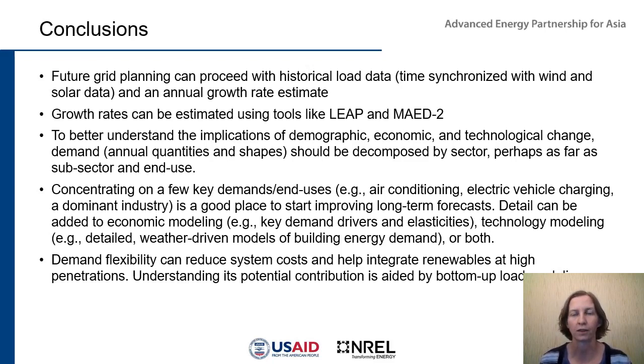So if you're thinking there's going to be a lot more electric vehicles, or there's going to be more uptake of air conditioning, or if there's a key industry that is a lot of your demand, then you might want to take a closer look at those things, and you might want to make a few different scenarios of how those loads might change into the future, and that might give you a better estimate of how loads might look. And if you do that scenario bracketing, then you can get a range of looks and be a little more prepared for the range of possibilities that you could be seeing.